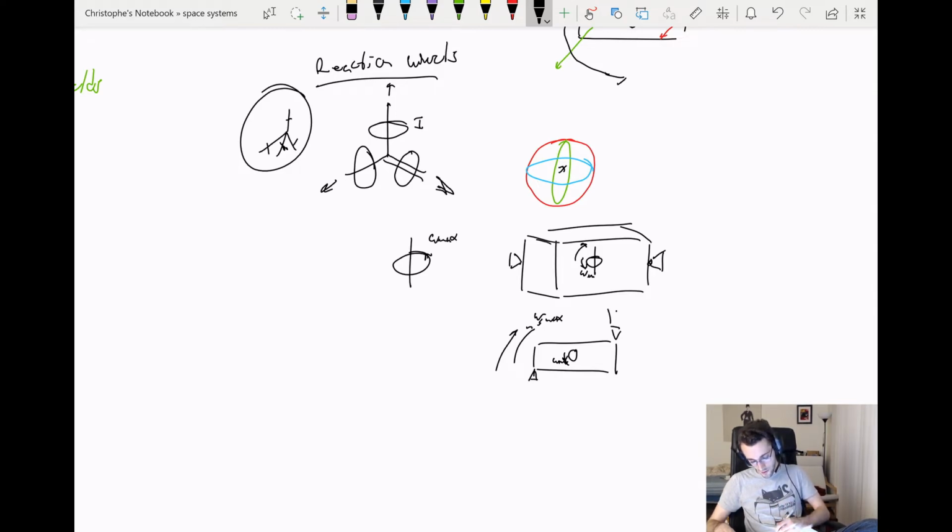So we spit out our fuel to speed up in that direction, but we slow down our reaction wheel so that our omega remains the same, but our reaction wheel is going a lot slower. Which means that, hey, we can speed that reaction wheel up again to get even faster angular velocities.